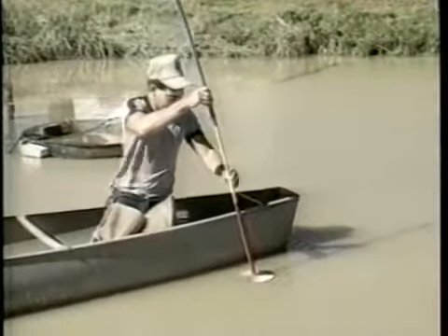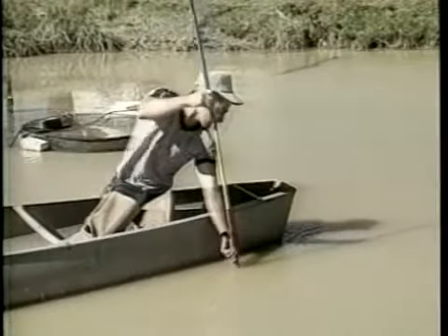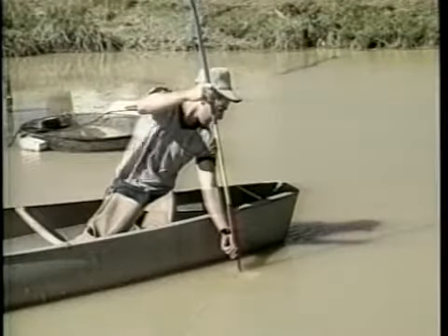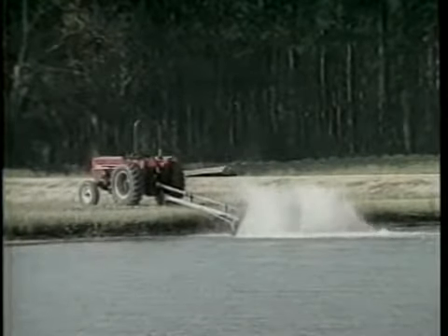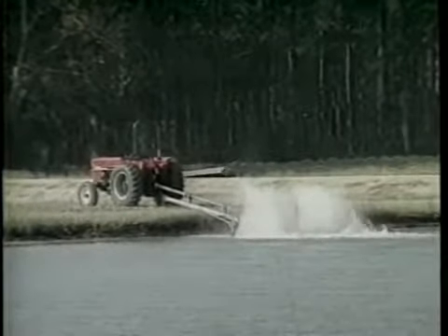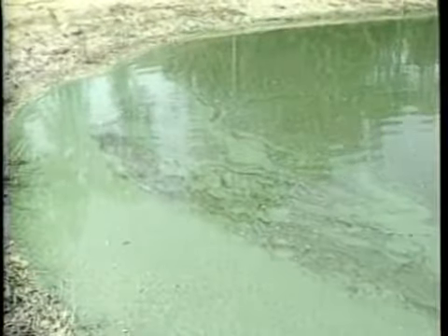Therefore, the Secchi disc visibility is only a simple indicator of abnormal conditions. Heavy blooms in which Secchi disc visibility may be below 30 centimeters are usually transient, but under certain conditions may be a chronic problem. Usually, overabundant phytoplankton should not be reduced by chemical treatments, since sudden reduction may cause problems with dissolved oxygen. However, in some cases, such as in ponds with dense blue-green algae blooms, chemical treatments may prove to be beneficial.